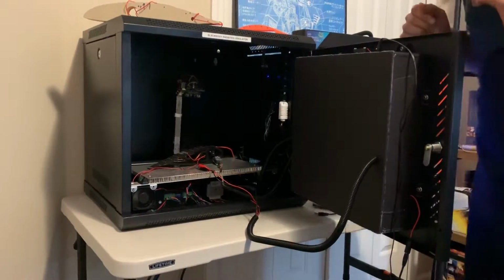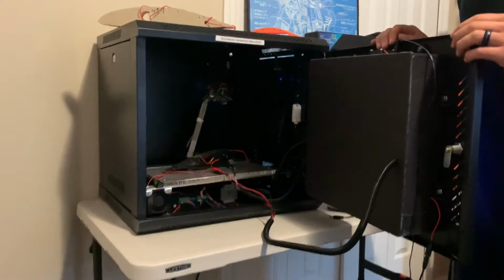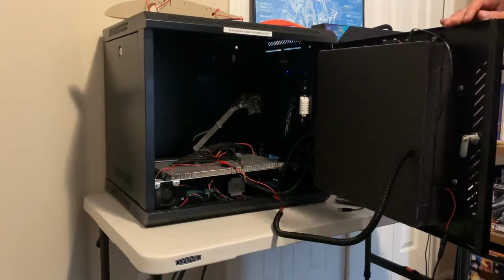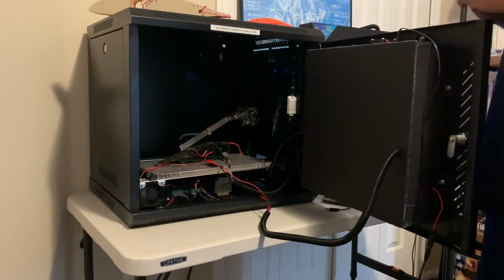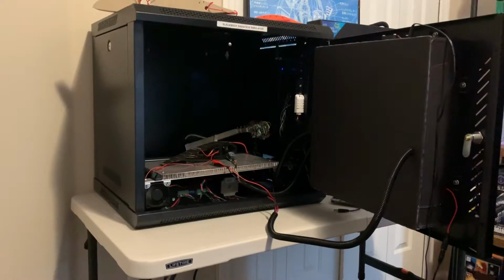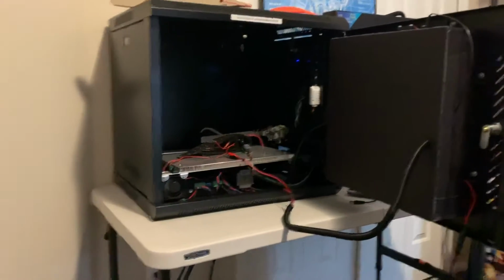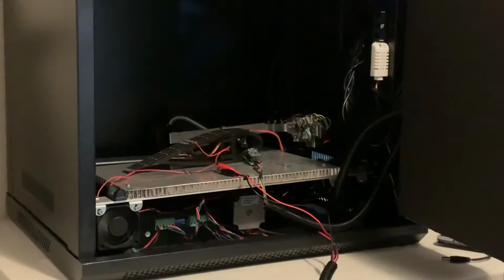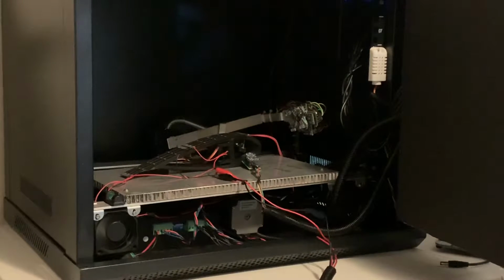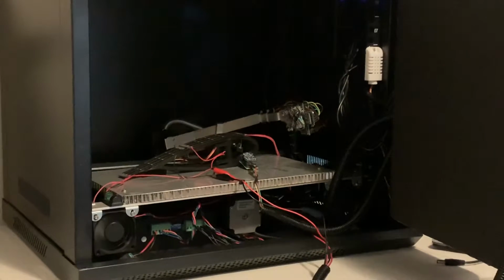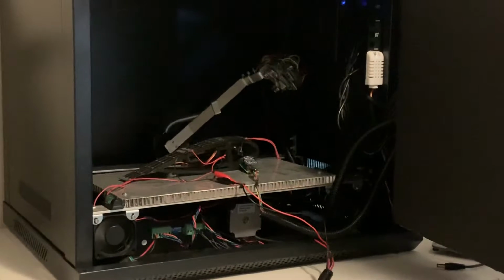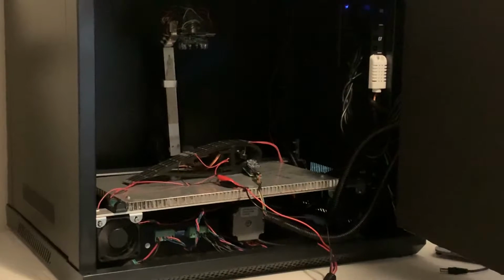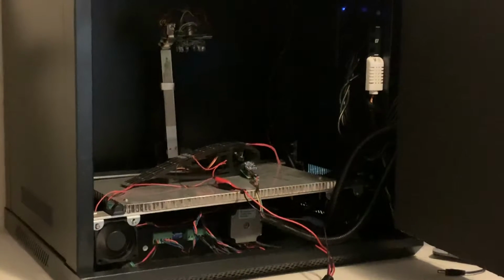Lots of different fans, got to keep it nice and cool. So the artificial sun module subsystem is actually going to what I call a zeroize condition. Since it's emitting a specific wavelength of light through different beta angles, it needs to be consistent and make sure it's going to a zero condition. Okay, so my beta angle position and control system is normalized, and what I'll do is I'll put it right back up to the 90-degree position. Sometimes I accidentally only hit 40 steps instead of 400. So it'll go through its full sweep, zeroize, and then you can put it right back up to the 90-degree position. So what we'll do is we'll take a look at the interface.